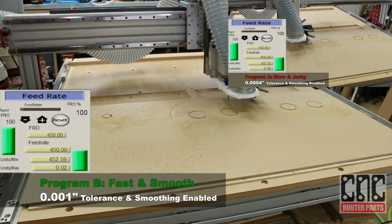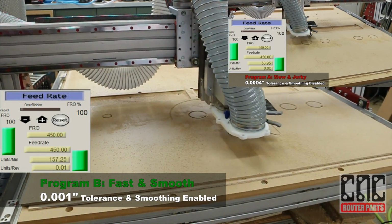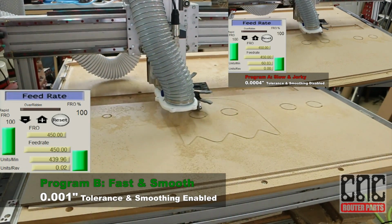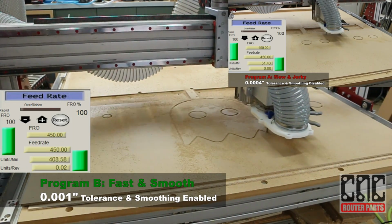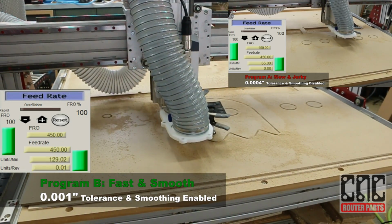Let's compare these two programs again in a bit more detail and talk about some of the more subtle but important clues that our program might benefit from tuning Fusion tolerance or smoothing settings. One symptom you may notice is perhaps your program is only averaging a fraction of your program feed rate, such as program A in the right hand corner.